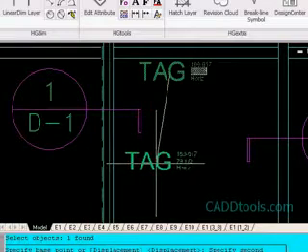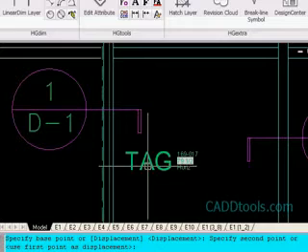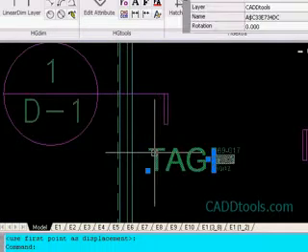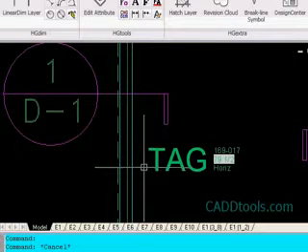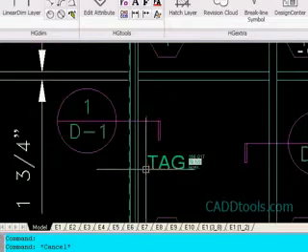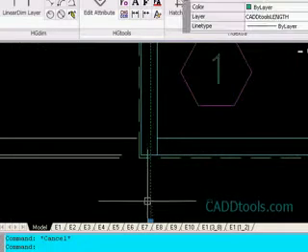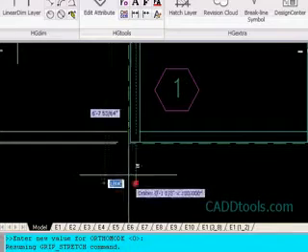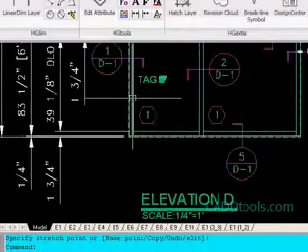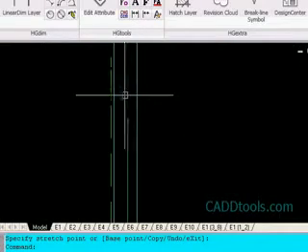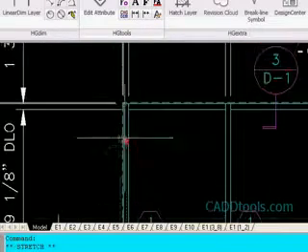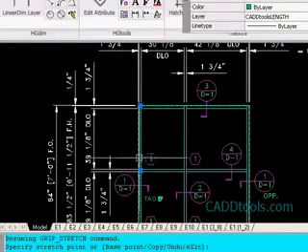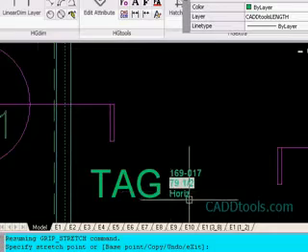Now the attribute data is separate from the line, and later on we will group them, so when you select them they'll both be selected at the same time, which in big drawings will help later on. And since the data is associated with this line, as you change the line, AutoCAD automatically will change the dimension in the attribute data.